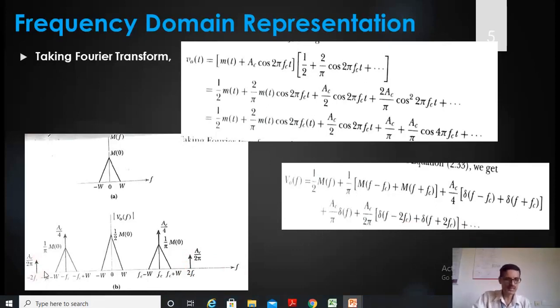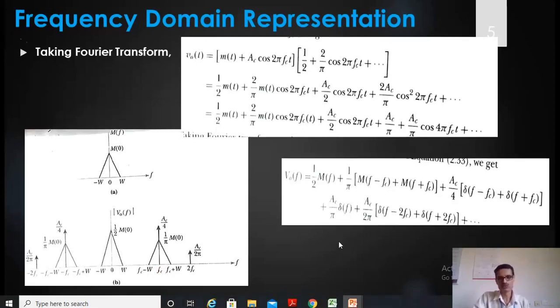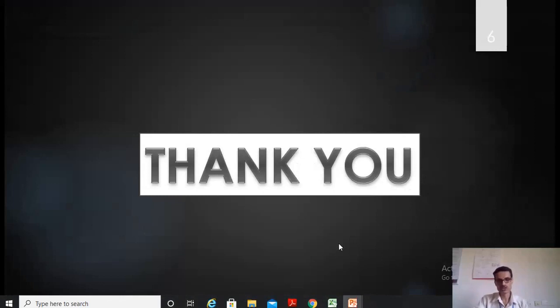Now what I will do is, I design a band pass filter which is used to allow only this component. So this is the ideal characteristic of, say, a band pass filter. So I will draw one band pass filter characteristic curve over here, which is used to allow only this component. Okay, that is 2 sidebands and 1 carrier, unmodulated carrier. So hence we get a conventional AM signal by using switching modulator. Okay, so thank you for watching this video.